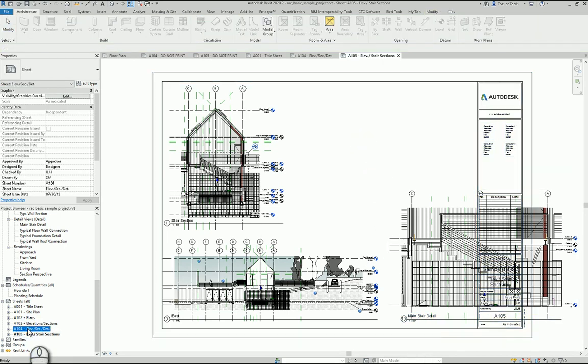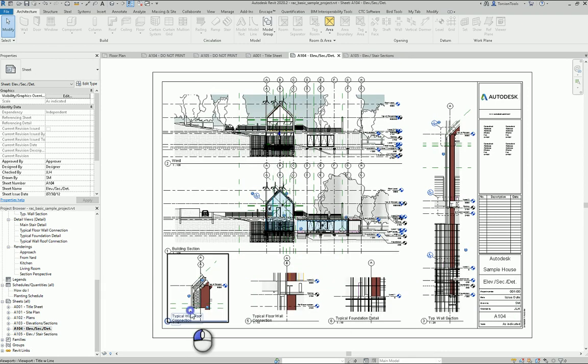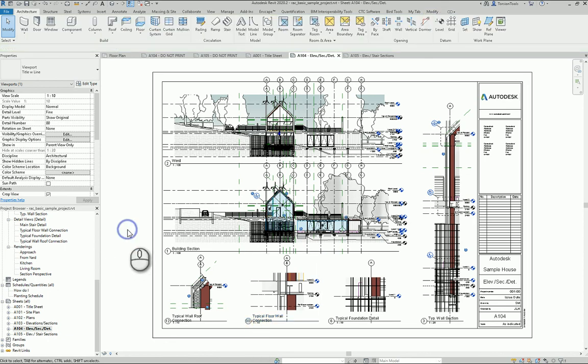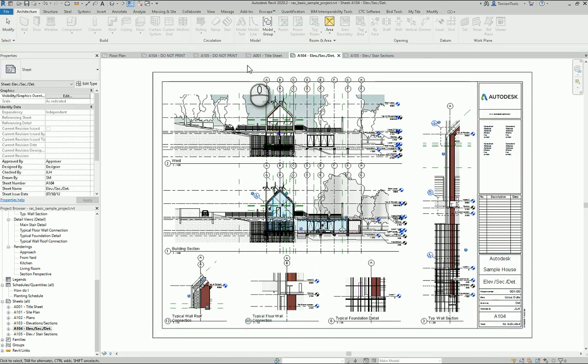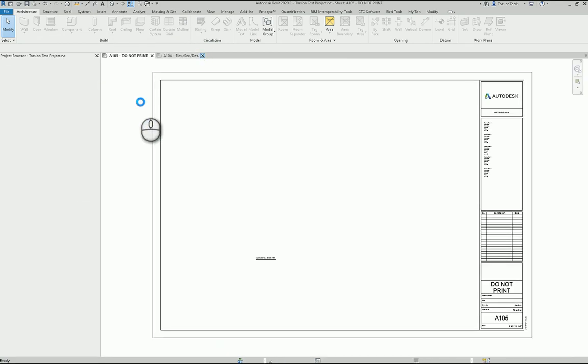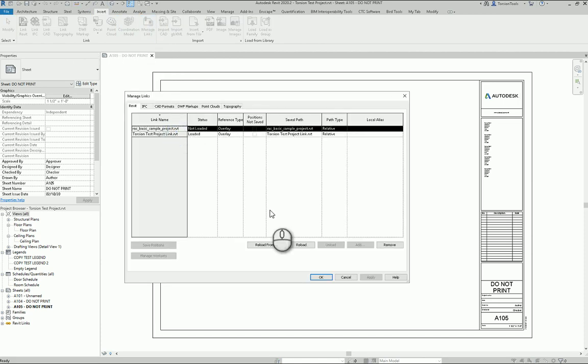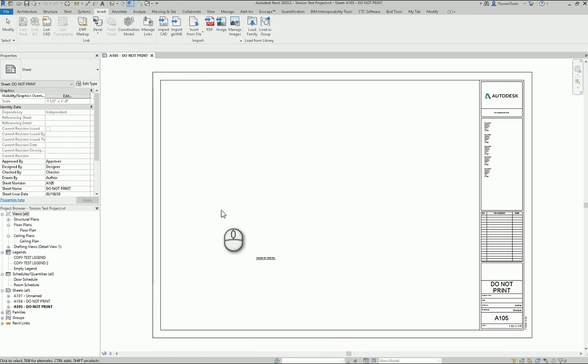And then even back over here on A104, I'm going to rename this one 12 and this one 00 for reference. Okay, now if we save that project, close it, and come back over here, make sure we reload that, because it only looks at loaded projects. So if there is a linked model that is not loaded, neither of these tools is going to see that link in the project.